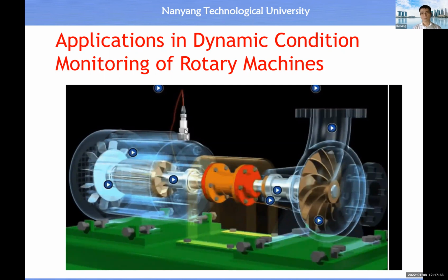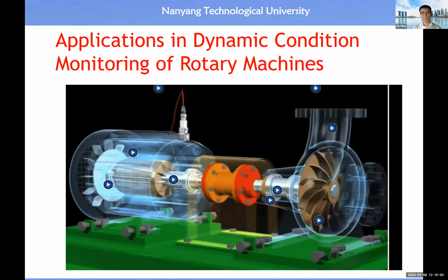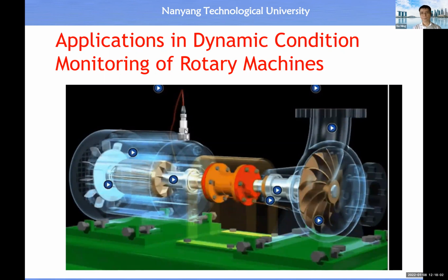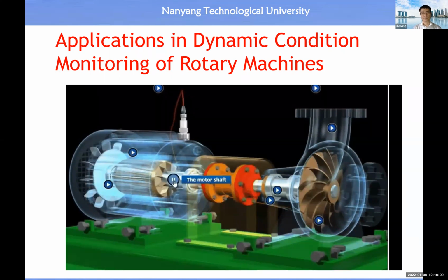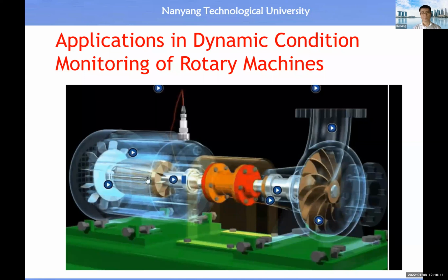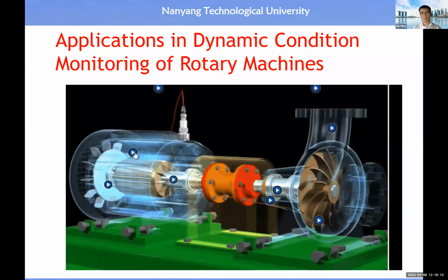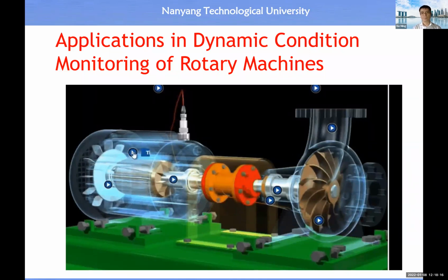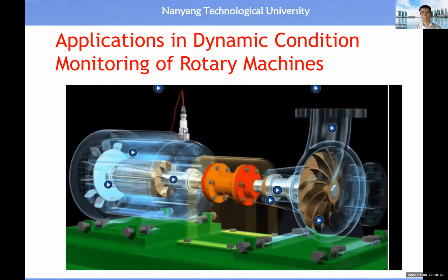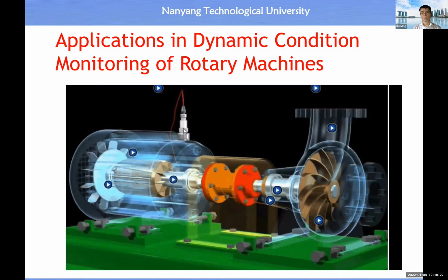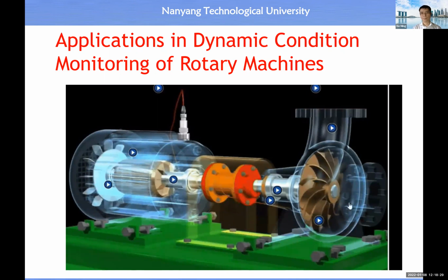But one of the keys is that vibration analysis, in a sense, enables us to sort of listen. Well, what is happening with the shaft? What's happening with the bearings? What's happening with the rotor bars? Now, we pick up all those sounds from here. They all combine together into one measurement, but separating them in frequency and some of the other things we'll explain lets us do that so we get an idea of the health of each of those components. Over this side, oh, that bearing is not in good condition.